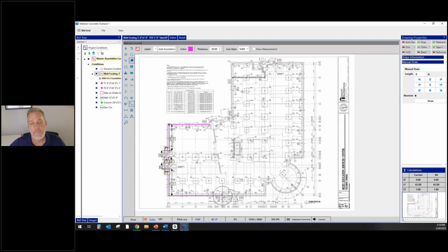We'll go here. Let's go all the way through those and then over. Now we've got a radius. With the Edge, you just click on the beginning of that radius, any point along that radius, and the third point, and we can hit this little convert to arc or the letter K, and you'll see it creates the arc for you. Right? So we'll go around the perimeter here and just get some measurements so we have some data to work with.